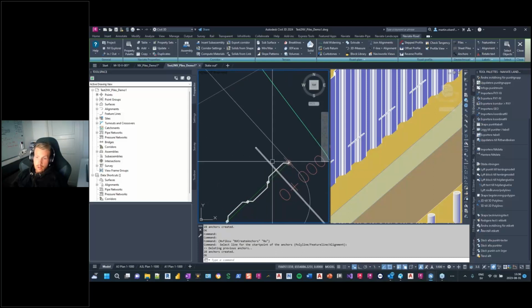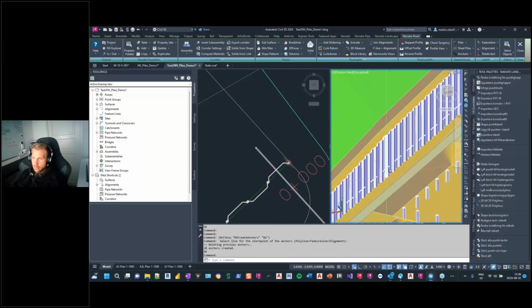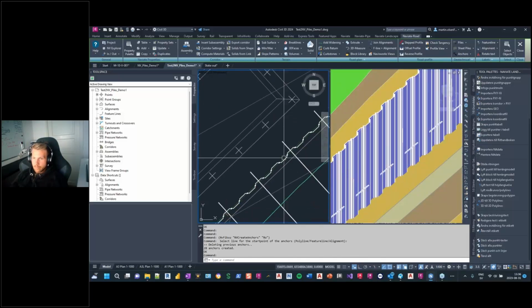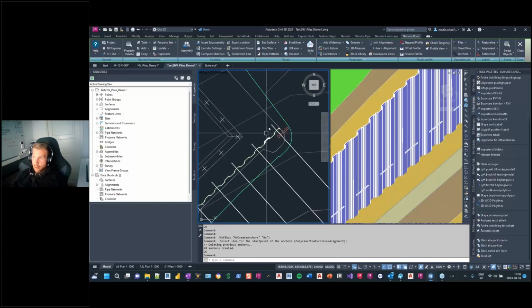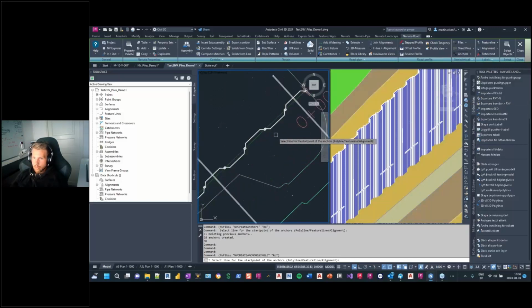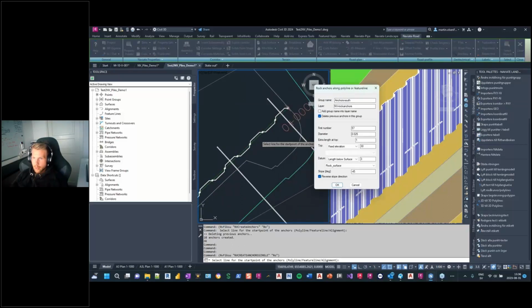And now I can see I got a better position for the first one, and I also got the slope direction in the right way. If I want an extra anchor, I can choose another function that is create single anchors. Just run that one, choose what line I want to follow, and it still remembers the setting from the other